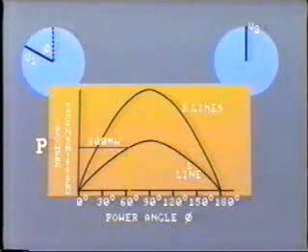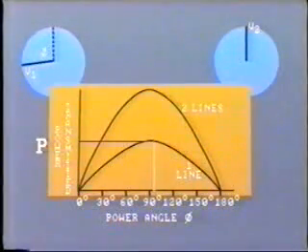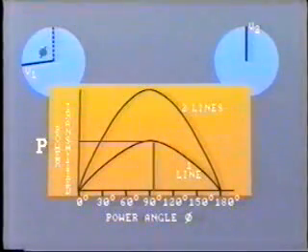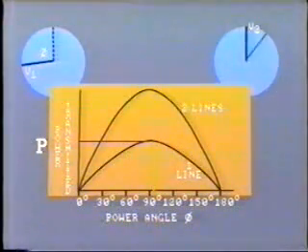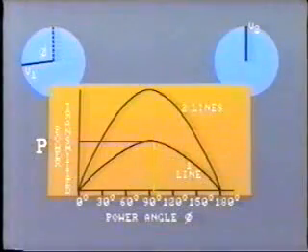Now, in this precarious situation, any disturbance on the power system, say a loss of load or a loss of power generation, may cause the voltage at V1 to advance further, or perhaps the voltage at V2 to lag, such that the load angle between them exceeds 90 degrees.